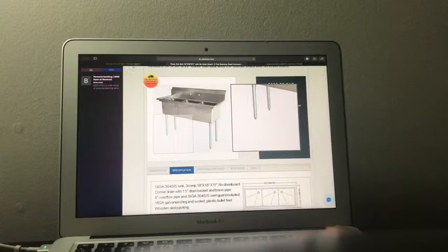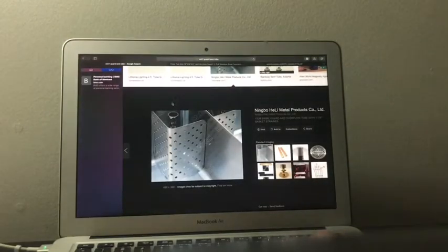And actually, we're going to touch on another thing here. You're not allowed to have food or grease going into a grease trap, and they mitigate the food with this style of strainers. And then you also can't have concealed overflow in a food preparation sink, and this overflow here would be one style where the water goes down in there.